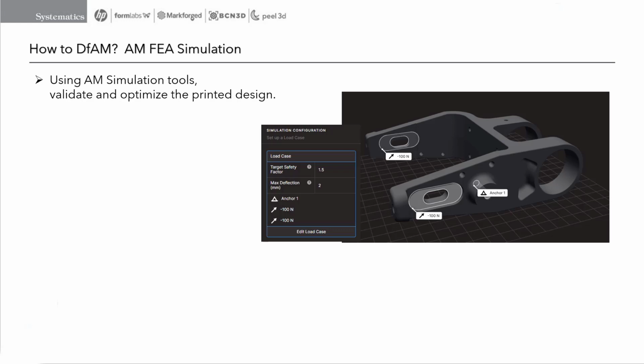Moreover, using the optimizer function, the simulation runs multiple times and generates print configurations that prioritize faster print time or less material, while ensuring the required performance is satisfied. Using print process simulation tools enables us to validate part performance and optimize print settings to ensure the part meets the performance requirements while maximizing manufacturing efficiency.